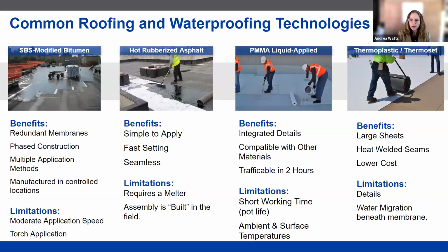So if we create our bathtub, we can go all the way up the sides with the same membrane, and it can form a seemingly unlimited number of detail conditions and configurations. Now, PMMA is known for its rapid cure time, which allows for us to complete roofs very quickly, or in this case, add additional layers of our overburden assembly, even the following afternoon or day.